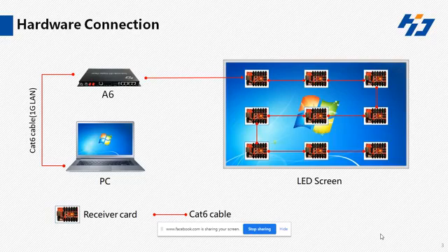So suppose I am taking an example where we are using 9 cabinets. Cabinets have 9 receiving cards. So what we have to do, we have to connect the laptop with the input port of the sending card, and the output port of the card is connected with the receiving cards respectively in the picture.